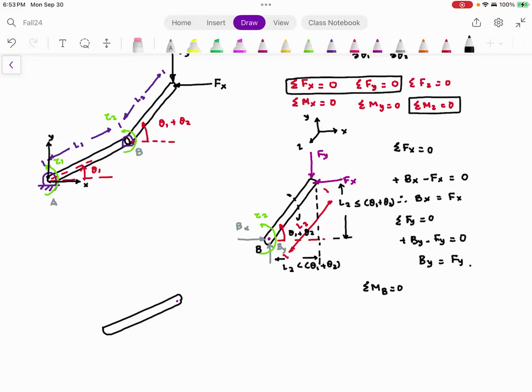Yeah. Why is it opposite from where the torque is going towards? Because, it doesn't matter. Conventions are for convenience. The most important point here is I started with the right hand coordinate system and I'm solving the entire problem in the right hand coordinate system. As long as my coordinate systems are consistent, to be honest with you, at this point, I do not know if the directions of tau 1 and tau 2 that I have assumed are correct or not. If the directions that I have assumed are incorrect, then in the answer, the sign will be negative.